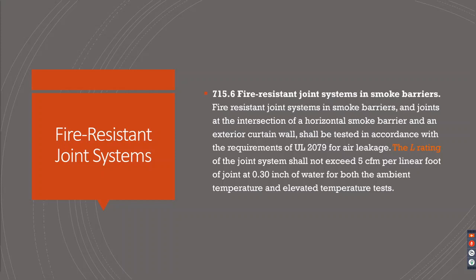The L rating of the joint system shall not exceed 5 CFM per linear foot of joint at 0.30 inch of water for both the ambient temperature and elevated temperature test. So of course, you see some similarities with the L rating requirements for when you need it at the